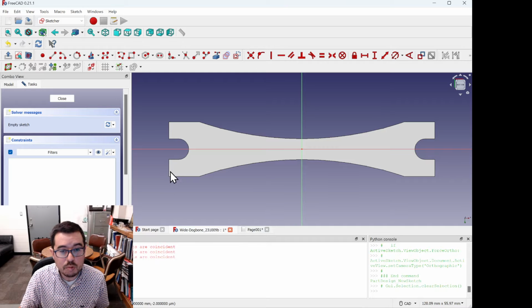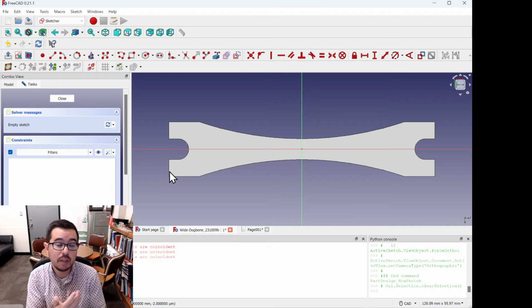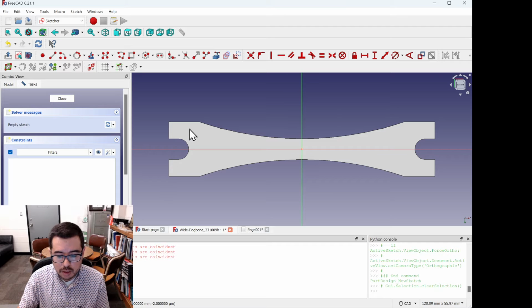This curved region is great, and we use it for laser engraving or cutting the samples that you're able to use and cut further. But for our finite element analysis, it's not necessary. So we're going to cut it away. What actually happens is the grip will come and clamp down on this region, and then put the middle region into tension when we pull it apart. So what are we going to do?